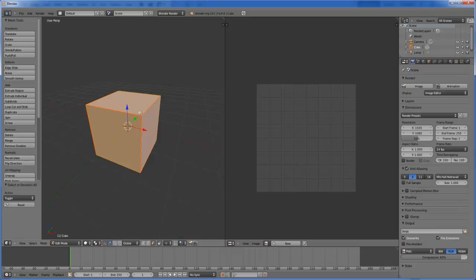Now if you press U, the command to unwrap, the menu to unwrap is in the shortcut key U. So press U and click unwrap, and you can see that the whole box is now unwrapped very nicely into a cross-shaped UV map in this viewport.